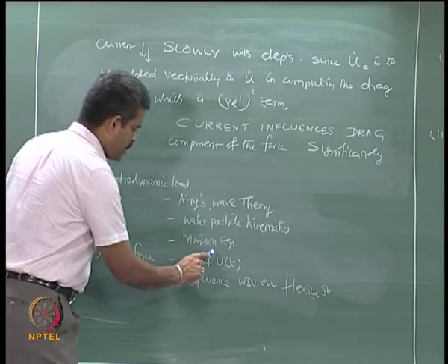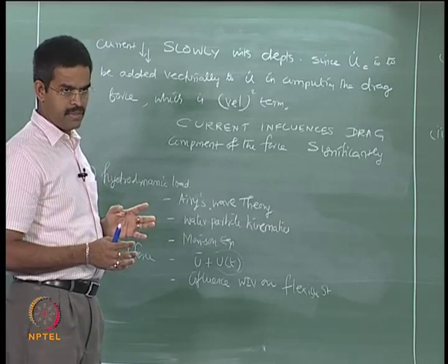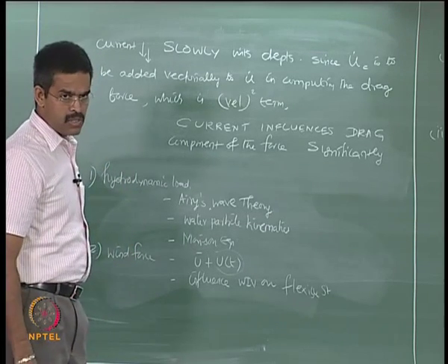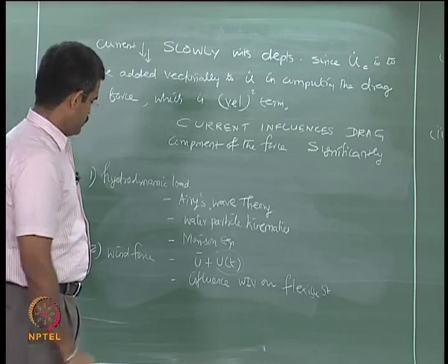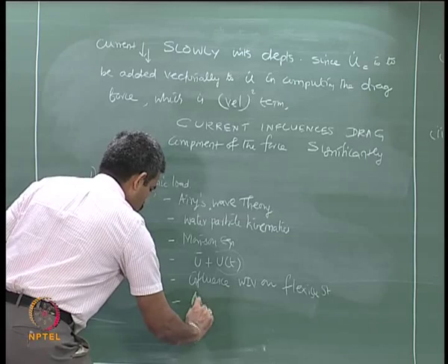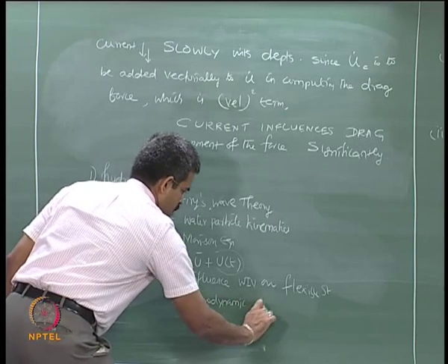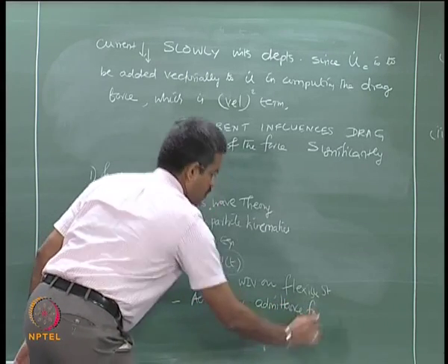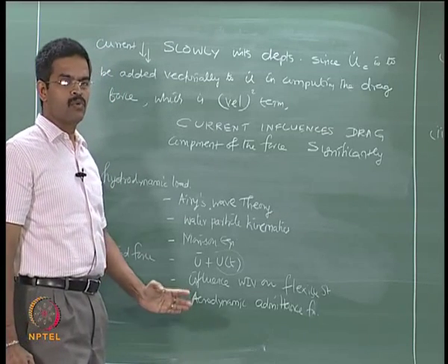So, how can the dynamic component or the gust component be handled, because one is a random process, how to handle this in a closed form solution? We have the aerodynamic admittance function, which helps us to handle this issue easily in computing the wind forces.